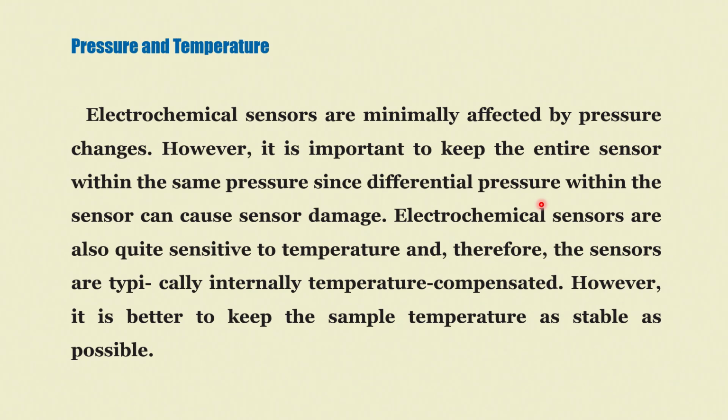Now, regarding pressure and temperature, that is another important aspect one has to worry about in the sensors. So, electrochemical sensors are minimally affected by pressure changes, hardly, because they all operate most of the time at normal temperature and pressure. It may be higher than room temperature in particular places or not, but they are not produced under any special environment. No, normal room temperature and pressure.